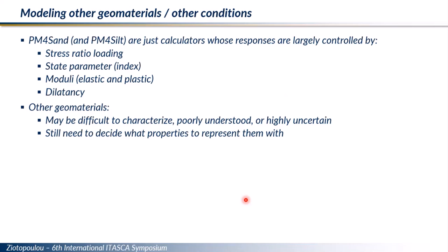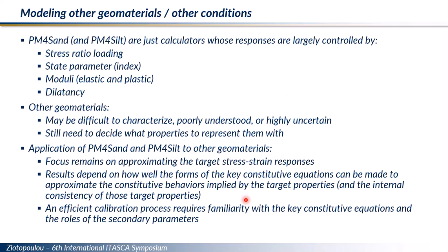But ultimately, we still need to make decisions, and we still need to represent them in our models. So we can focus on approximating stress-strain behaviors and having a good grasp on them. And ultimately, it has to do with the extent to which the constitutive relationships can match what you believe your soil is doing after having spent some time in the site characterization.